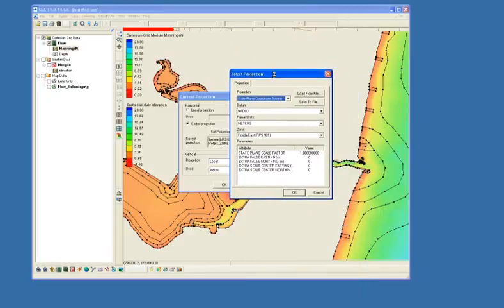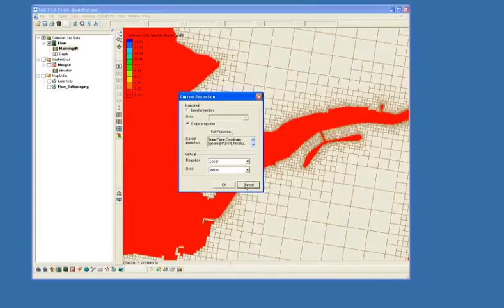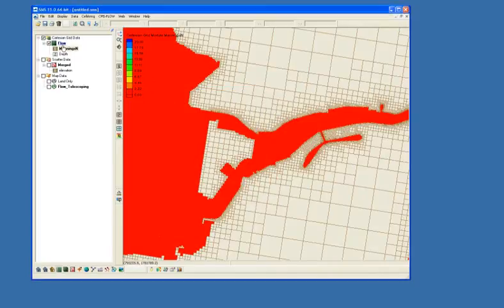and what we're wanting to use for this zone is actually New Jersey State Plane. And when you set the projections and build the grids, the projection information is automatically saved with that grid as well. So SMS knew that this grid was supposed to be in a different coordinate system. And so you could actually right-click and tell it to work in the grid projection. And when you do that, it will reorient the grid and set us in the right projection to be working for this grid. I hope that's pretty clear.